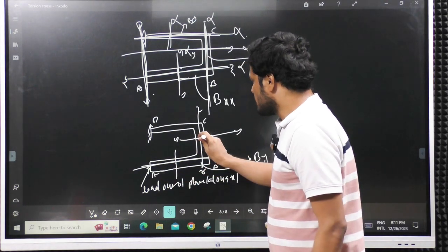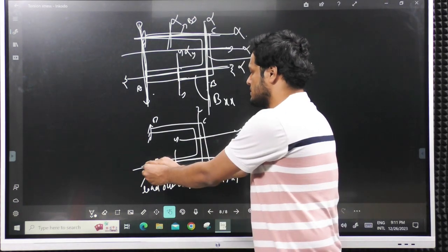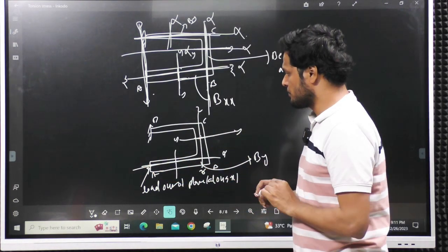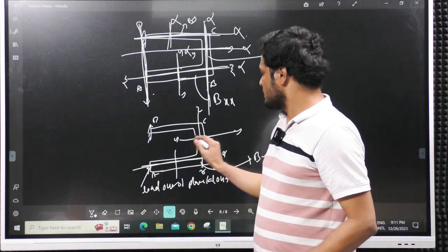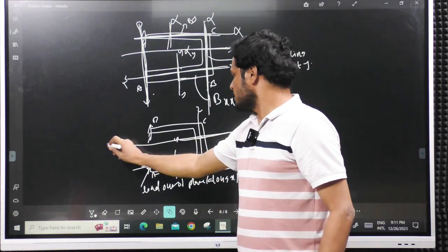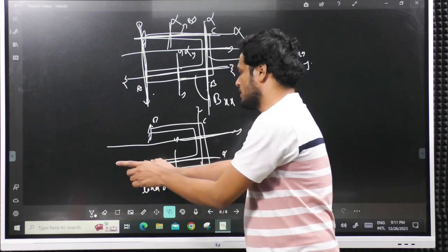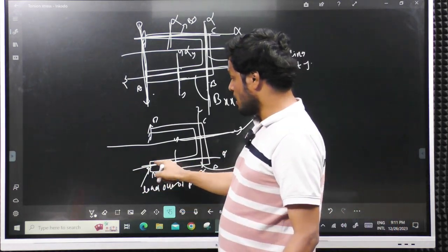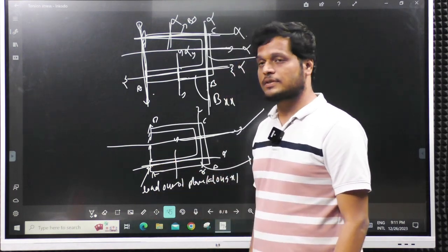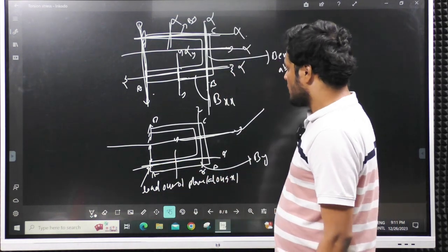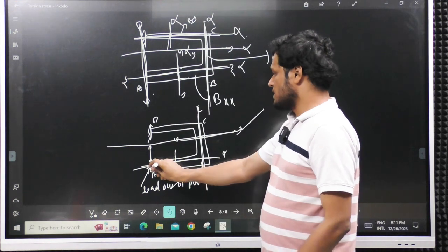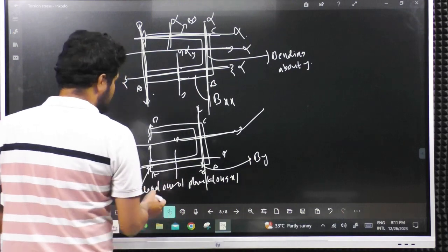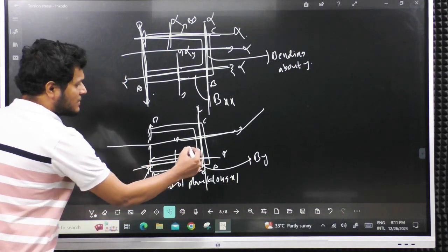So this and this are parallel, the load is like this, x axis is like this, both are parallel, I can remove. Okay. Next, the load is like this, even if you extend this and extend the load line, it is not meeting anywhere, so it is having eccentricity about this load of this much eccentricity. Okay. Next, coming to torsional axis, this is not meeting the torsional axis also, so with respect to torsional axis also, this has an eccentricity.